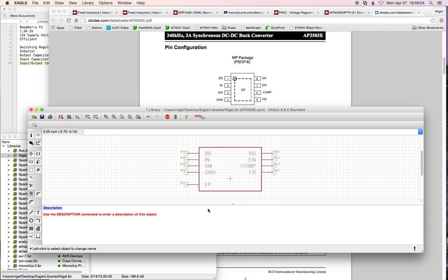Now in the schematic, we'll just connect the exposed pad to ground logically via a wire, and then when we're actually getting to laying out the board, we'll make sure that the ground plane covers both. So that's kind of the general term here. We've got a lot of empty space here in the middle, so I'm probably going to bring this in a little bit. I'll grab my move tool, bring each side of the box in by just a tad, and bring the pins over to meet it.